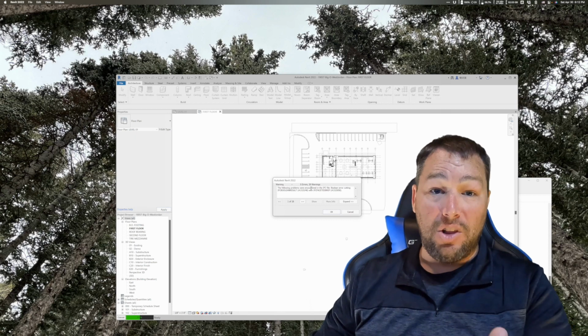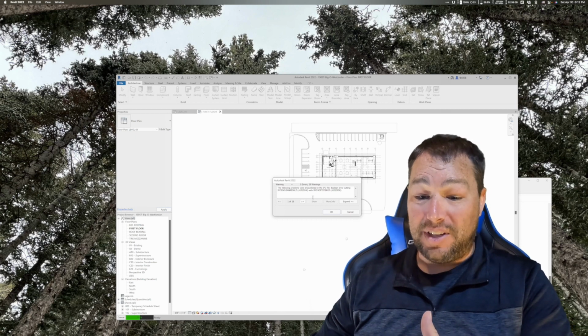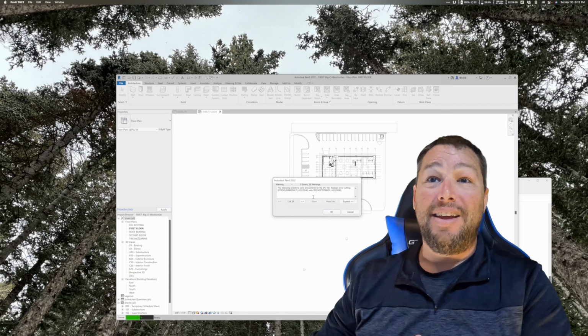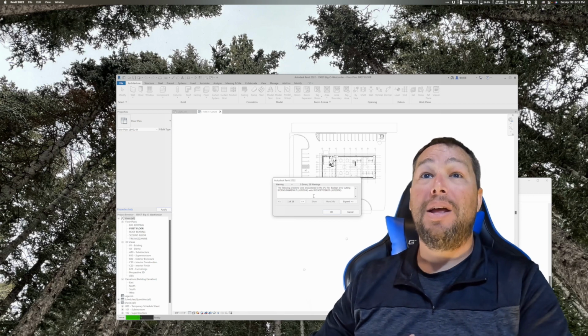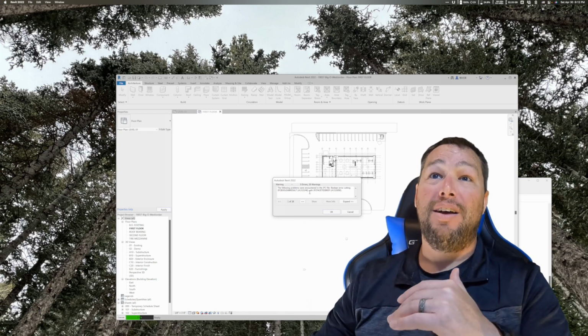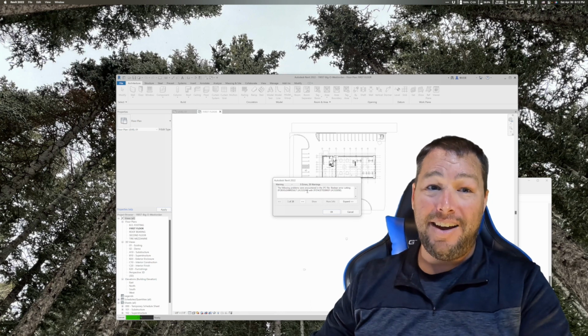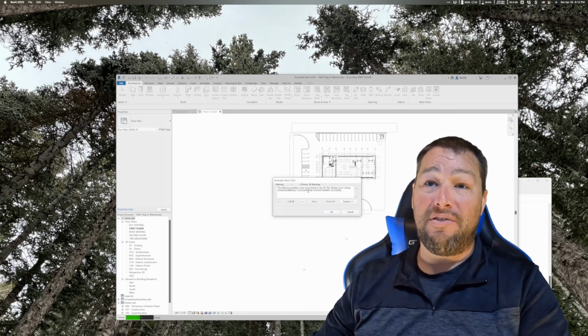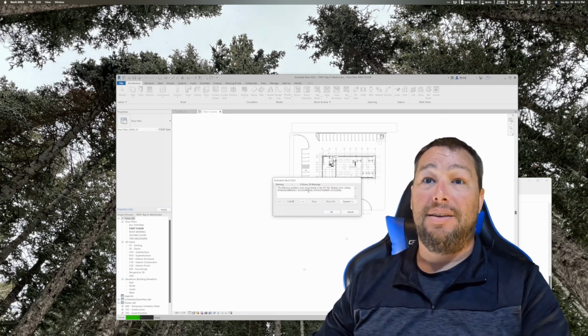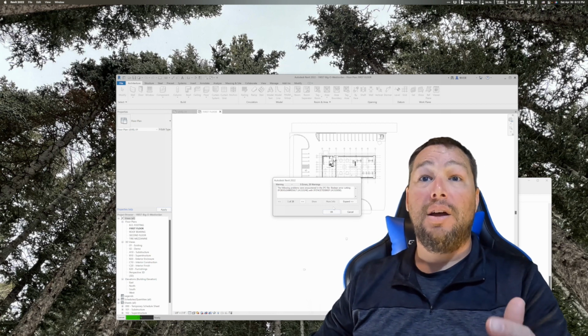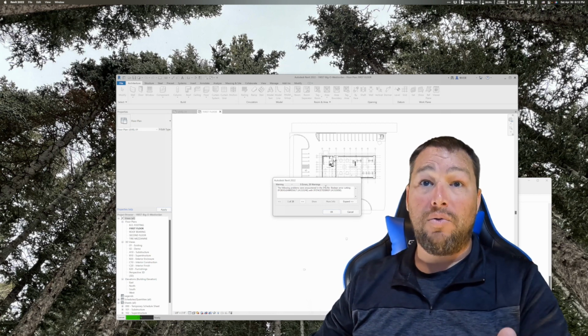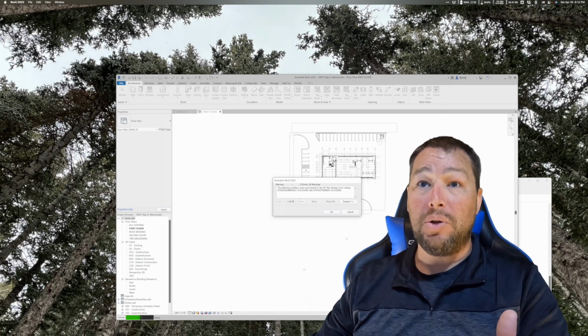Okay, after a long wait, almost half an hour in processing time, we finally have the Archicad-created IFC file in Revit. Okay, let's take a look. We've got 28 warnings. Fortunately, none of them are errors, but let's just see. We've got a Boolean error cutting.